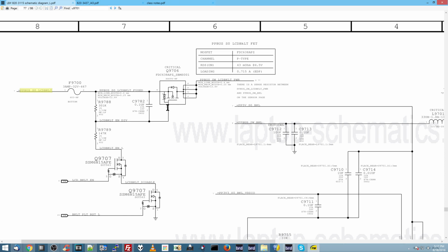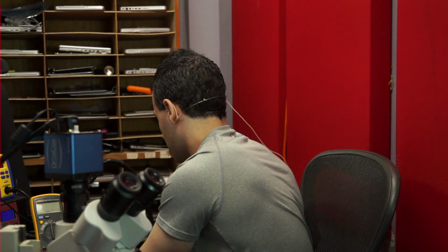Another thing I'm going to notice as I take the machine out of the computer is that I was this complete idiot, and that I didn't check the voltage after the fuse, because it's very simple that the fuse itself could have simply blown, and that could be why nothing is working. So I'm going to check that right now before I do all this, because that would be really stupid if I didn't check the fuse.